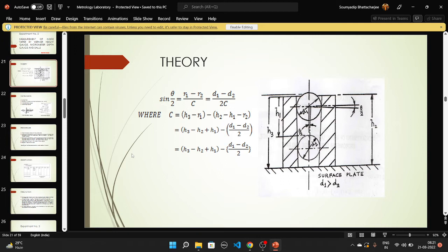Why do you need to take it? Because you have to go inside the job and over the small ball, so it will be touched by that extended small rod fitted with the micrometer. So do not forget to add that. Students often fail to add that when asked in the viva what the reading is at this position. They take the MS reading plus CS reading times LC, but they fail to consider the extended length attached to the micrometer, so that you can cover the whole depth inside to the ball of the given job.